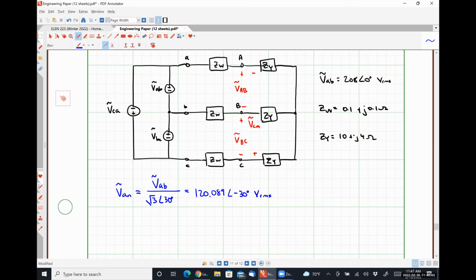This building that we're in right here, the electricity is distributed in what's called a 208/120Y configuration, where we have access to 208 volts line to line and 120 volts line to neutral, or Y connection. That's what our power lab is set up for and all that kind of good stuff.